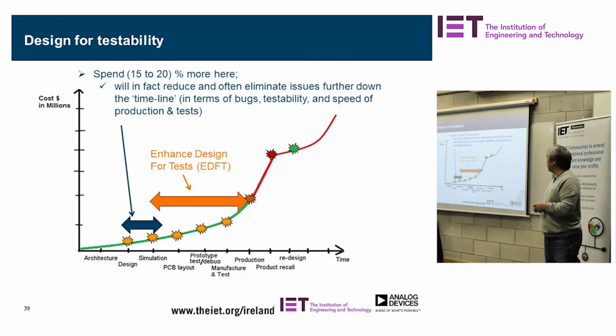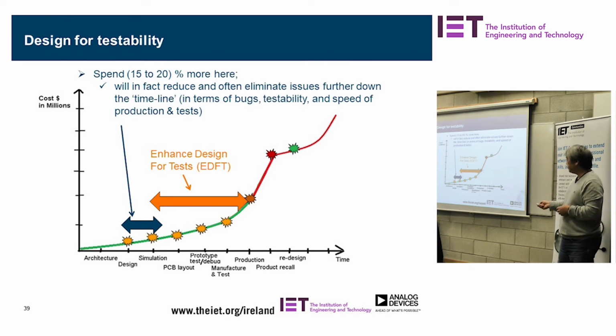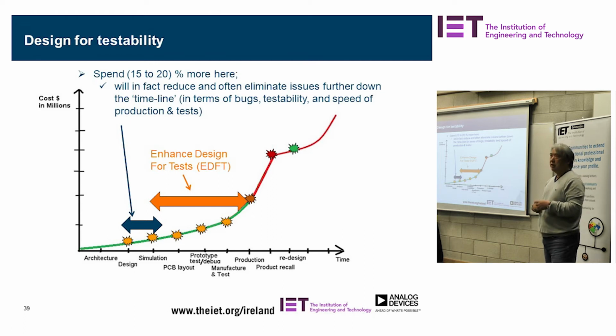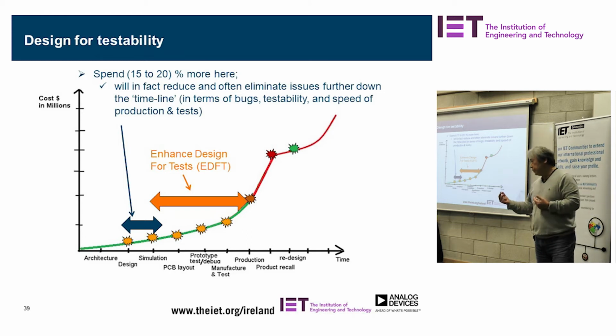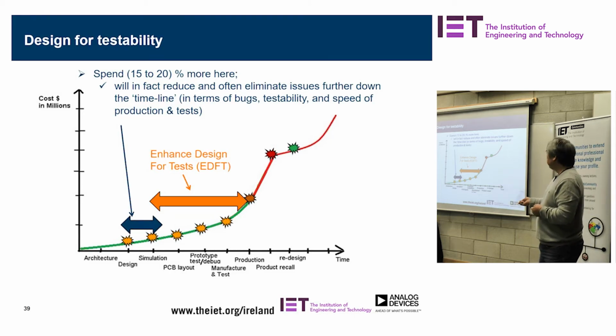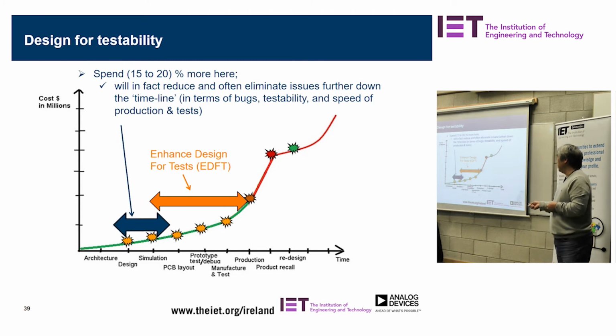So here's design for testability. I always find that you should spend some more time here and add in about 15 to 20% of extra circuitry in your design to test your design for testability. So you add a little bit more here.